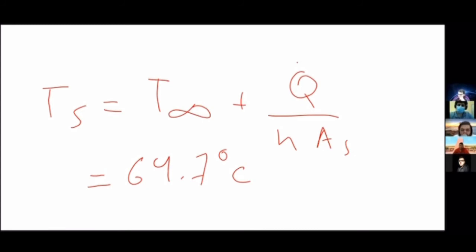Oh, so is that the total area including the transistors, or without the transistors? No, it's just the flat area. We're not talking about volume. We're talking about the surface area, which is 22 by 22. It's the contact area, because that's where the heat is transferred, on the contact area between the aluminum plate and the resistors. Okay, so in your equation next to the area of the surface, this is K, right?